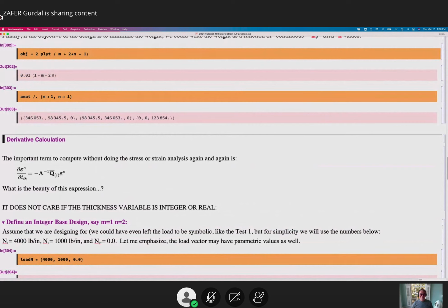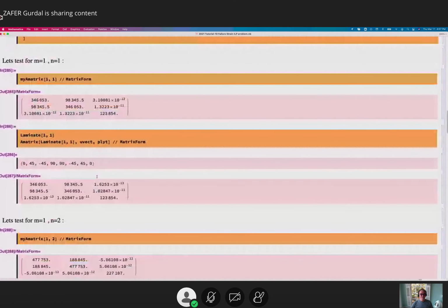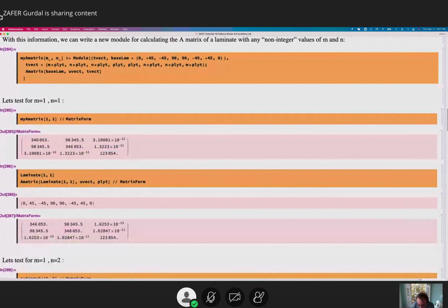And there, you're going to see that actually there may be some issues, because orientation angles are now in these Q's and Q bars. So the Q bar is not a constant quantity for orientation variables, but it is actually a changing quantity. So that goes back to, let me go to my lecture.